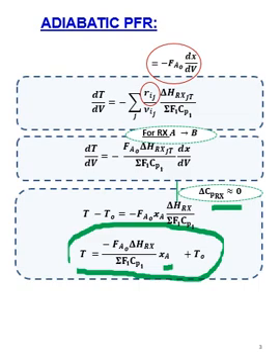If you perform the energy balance for a CSTR, you will see that I have exactly the same linear relationship of temperature as a function of conversion.